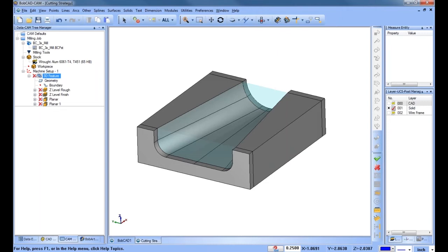The other thing that we're talking about is keeping the tool away from areas. You'll use boundaries in order to do that, or surfaces. Stopping the tool from going any deeper or having it cut deeper, you use top and bottom of job. And then extending toolpaths past the edge, you can use additional surfaces, but there are other methods that we can use as well. All right, so let's see here.